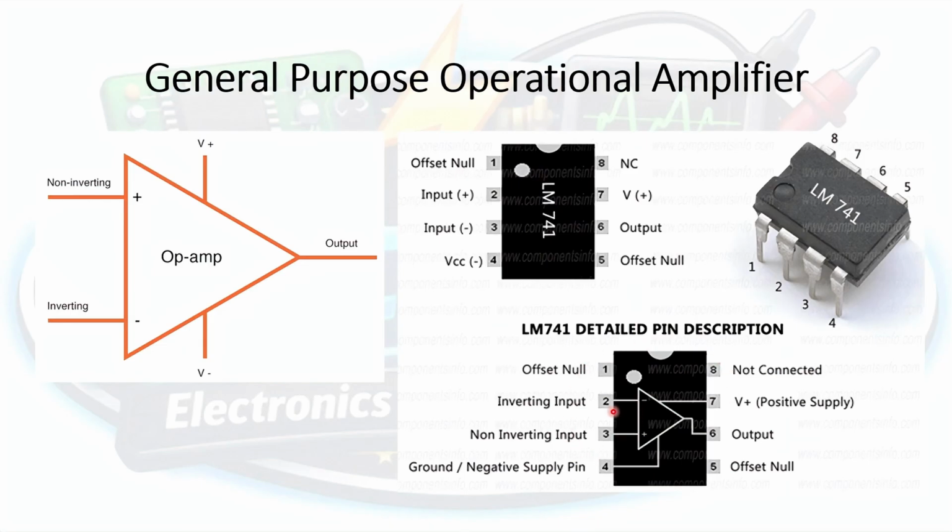The inverting input is on pin number 2. The non-inverting input is on pin number 3. The negative supply pin is pin number 4. The positive supply pin is pin number 7. And the output is on pin number 6.